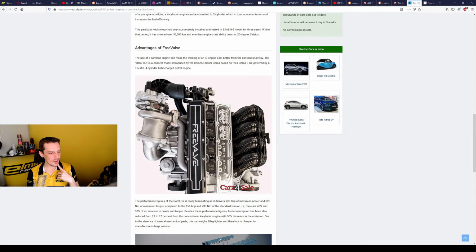Okay, but this cylinder head stuff is not smaller than a traditional one. You have those huge overhangs here on the back, and you have overhang at the front also, so a traditional cam type system with valve return spring can be made more compact than this free valve test system. This is the thing I remember seeing, so I think they have the dual action type, where you have one exhaust valve going into the turbine, and one bypassing it and going straight into the exhaust.